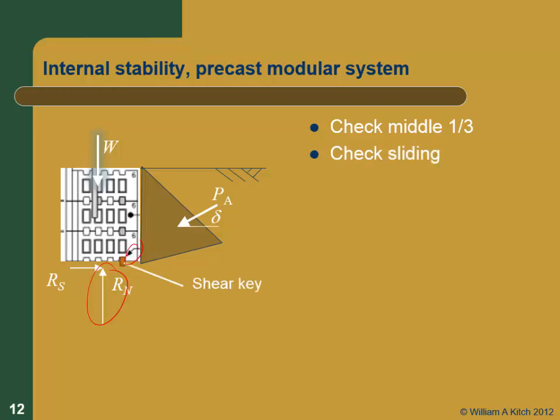Now in this case, there's this little key in there that's specifically designed to mitigate sliding problems. And the actual design of that and the sizing of that, you don't have any control over. You don't know what they did. They're going to give you some design guidelines, and you're going to hope that they're right. So my caution with these things is that if you've got a critical design, if you're doing a 15-foot high wall, it's probably not an issue. But if you've got a critical design with these, you better spend some time talking to the designers and satisfy yourself that they're doing it right.